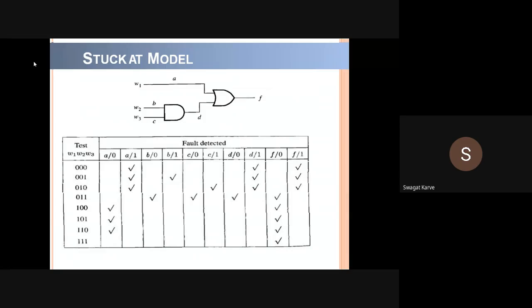And also with the output wire F, you have to connect it to logic 0, apply the test sets, check the required output, again connect it to logic 1, then apply the test sets and check the output. In this way, you can find a fault in any of the wires present in the circuit. So in this way you can carry out the fault model test.